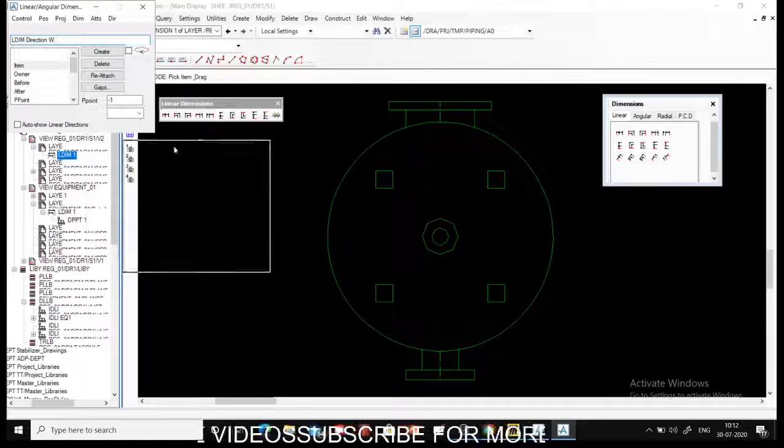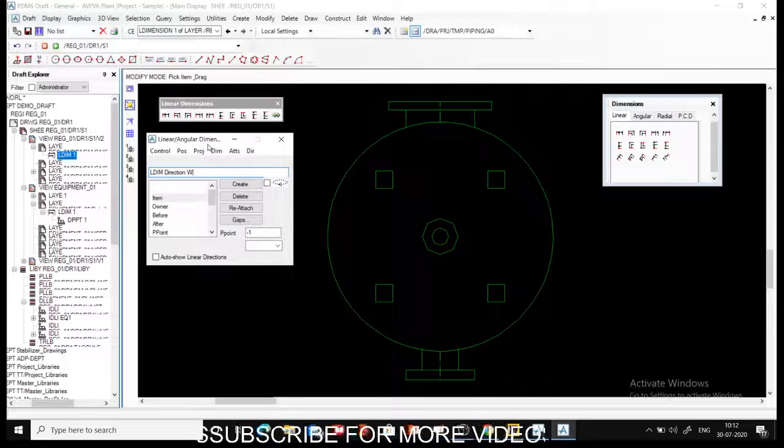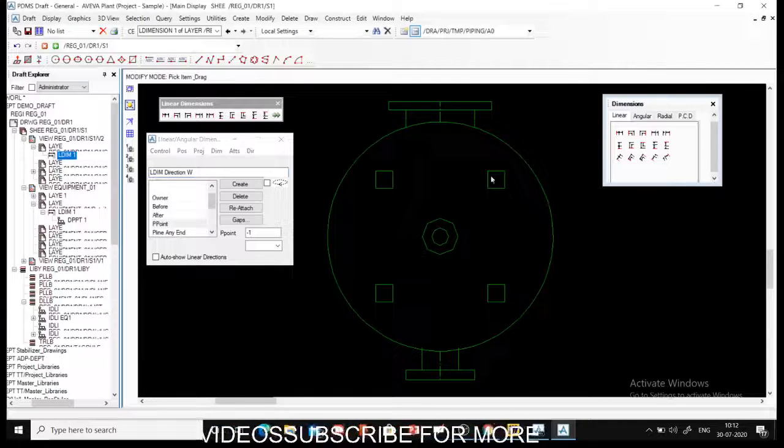Once you click on any dimension, a linear angular dimension dialog box will open, and it will give a label to that dimension, and there are various selection options. It is always better to go with pick points so that you can easily pick those points from the screen. You can also give it with the items, and even 2D and 3D cursor points you can use. I prefer pick points, so I can easily pick those points, and then I can go for create. This will only create one dimension.